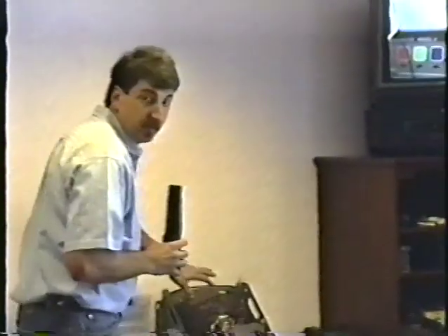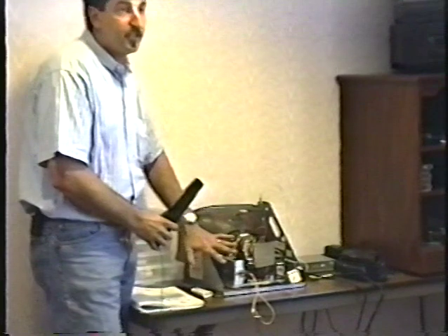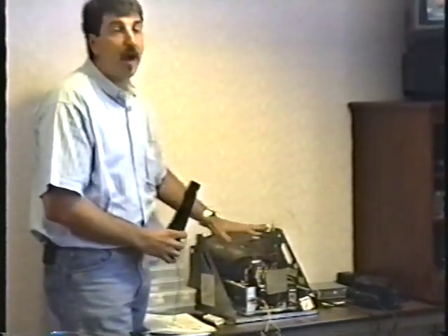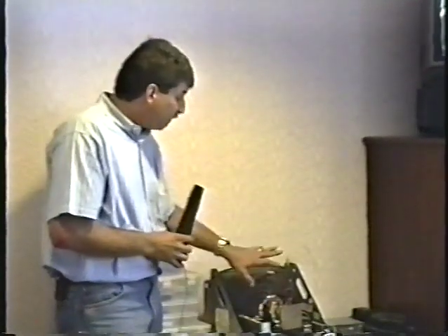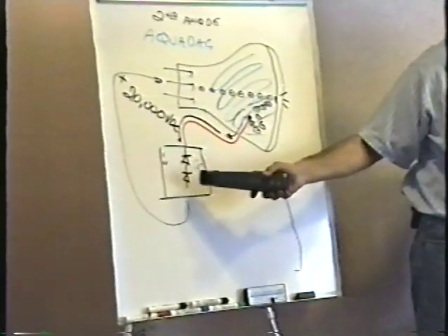It was pretty funny. But the point I'm making is that I know people that are perfectly competent technicians that work on logic boards that are just scared shitless to work on a monitor because they don't know what they can touch and can't touch. And the point is that not only can I touch anything with the power on, but I can work on the board, I can test transistors, I can solder, I can replace transistors. I do not have to worry about getting a shock. It's impossible for that charge to get out of the picture tube and out of the high voltage unit because of these diodes that are here.